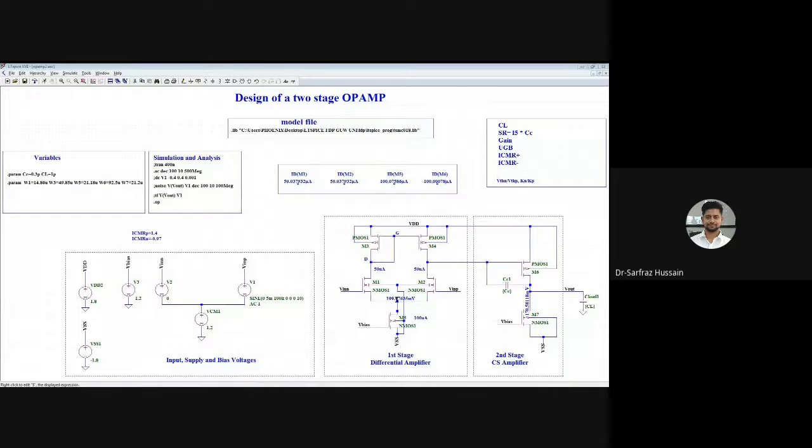So we will fix this one to a certain value. For this case, I have fixed it to 200 millivolts. This value you can also choose according to your needs. So how can we choose that? What you can do is first use this property, V bias and VSS. You can give a biasing voltage over here, or you can just calculate it using the VGS.